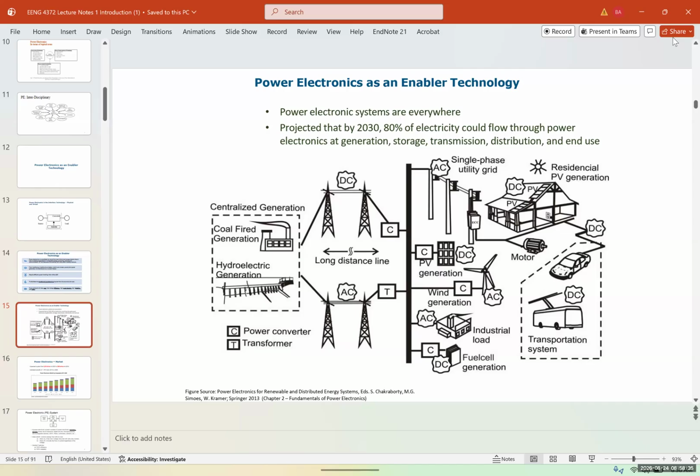If you heard about BMS, battery management system, it's a delicate balance between how much you can deplete and how fast you can charge a battery. Without a BMS system, let me give you an example. The first electric car mass-produced, technically, not the Chevy that came, that was not mass-produced, was the Nissan Leaf. When it came out, 2005, 6, something like that, the claimed range was 100 miles, 110. But quickly after 2-3 years, the range dropped to 20, 30 miles. Now, if you find a used one, it's like 10, 15 miles, something like that.